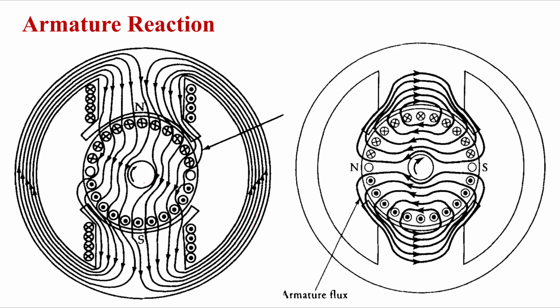Therefore, we need to shift the neutral plane as per the loading. As we vary the load, every time we need to change the neutral plane. Is it possible in practice? It is not possible. We cannot change it every time we change the load.